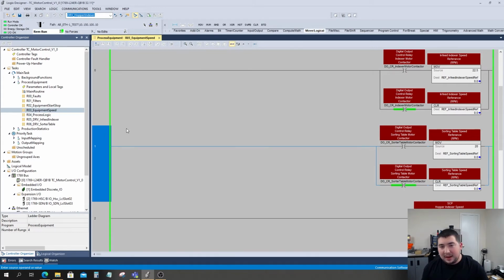However, that kind of takes away some of our ability to do other kinds of speed control. And if anything else, the one thing it won't allow us to do is directly control our acceleration. It's just whatever the drive is set up to do. So by making it in the PLC, we can actually have more control as programmers.